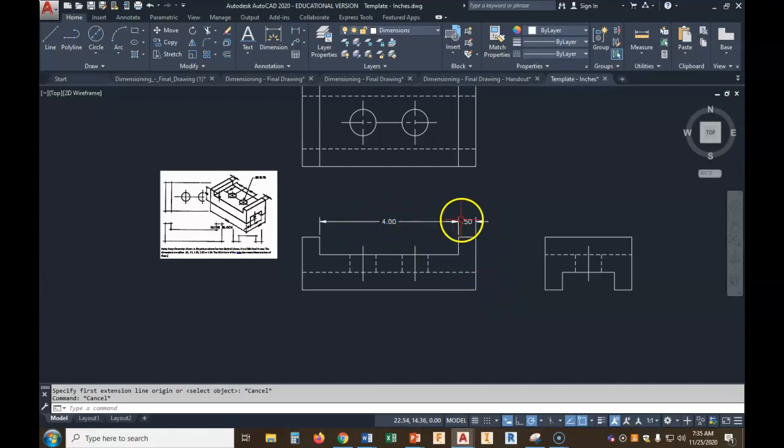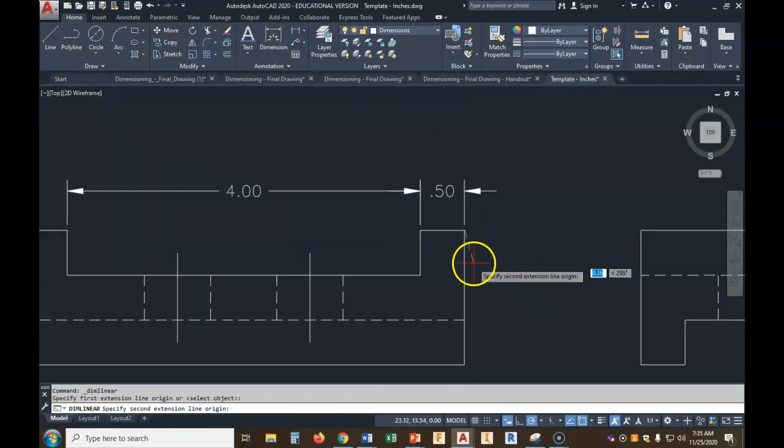Okay? So that's what we need. So that's located left to right. That's considered the size. Okay? Now, how about up and down? Again, that's the location. Some people say it was size because that's the depth of the cut. Either one's fine, whatever you prefer to call. So where do we start? There, that endpoint, see where I'm at? Now, we want to start at this corner because that's the furthest corner to the right. Click, drag out. There we go, and drop it in.